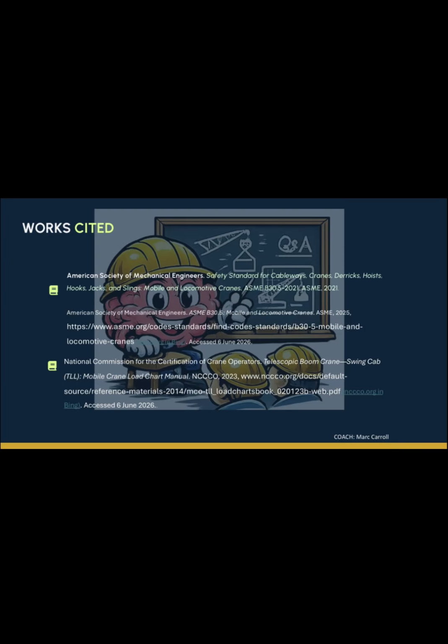You shall not, you must not exceed your rated capacities. You do not tip the crane to determine allowable loads. Do not exceed the maximum capacities.